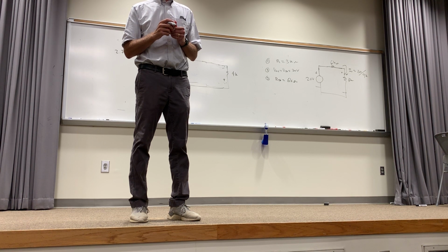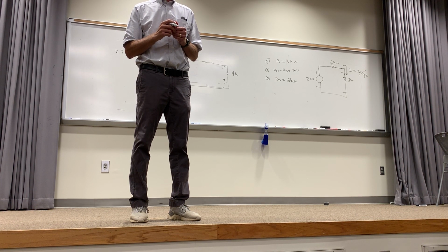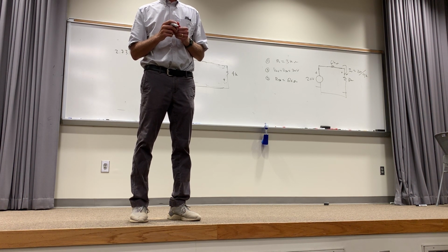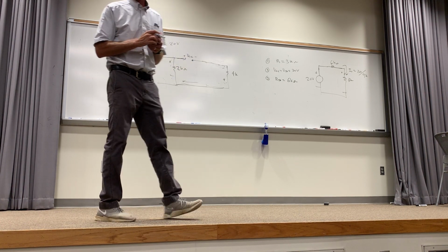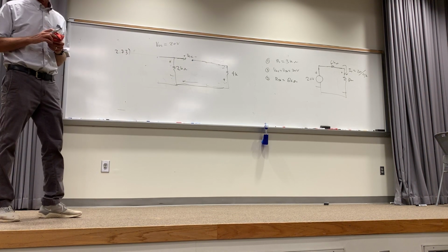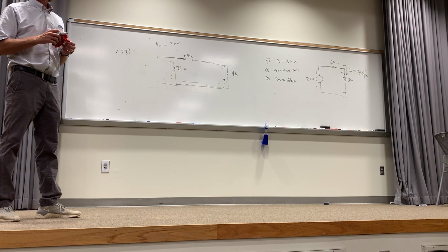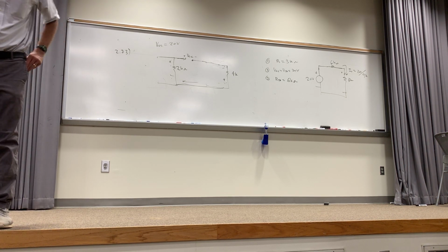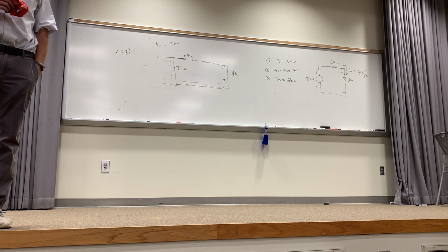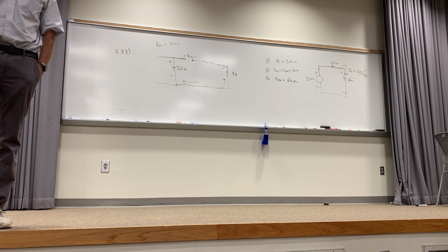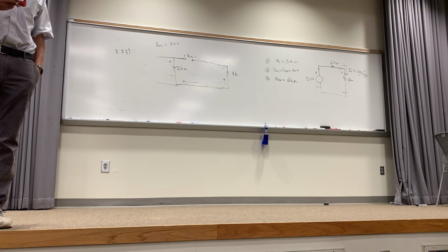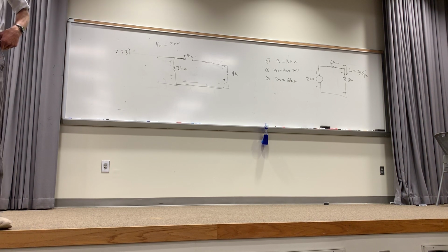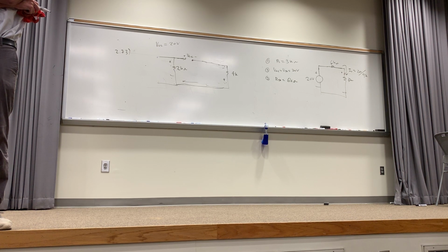Agreed? Yes. When you wrote the 12 volts next to that 2K ohm resistor, that was just the 6 milliamp current source. It was the current causing it, right? It was just circulating current. When you remove the load resistance, because we wanted the current through that, so that's the element we take out, you created V open and there was an open circuit between the two. You had 6 milliamps on one side of the open circuit and 2 milliamps on the other.